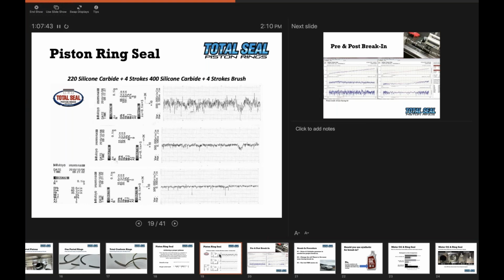If you think about sprint cars and that kind of stuff, they don't really need the gapless when the engine's at wide open throttle and at full temperature. The operating clearances then are really, really thin, and you've got all the heat working to keep the methanol out, and the methanol's evaporating. It's tuned right. It's when it's idling around and it's cold that the gapless ring provides the best contamination control for everybody. So in a street build like that, especially in Canada, that's where a gapless ring will be at its best, actually.